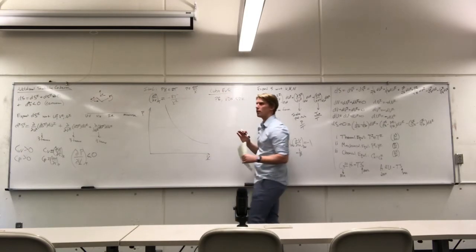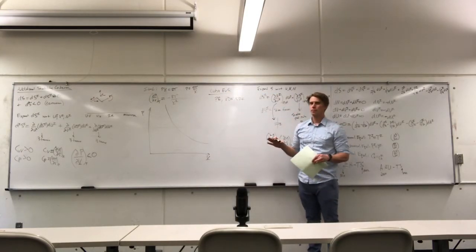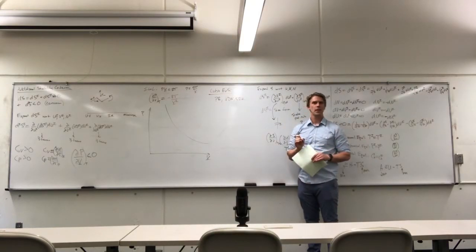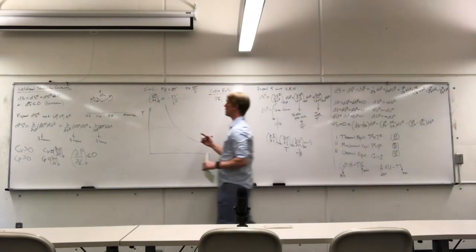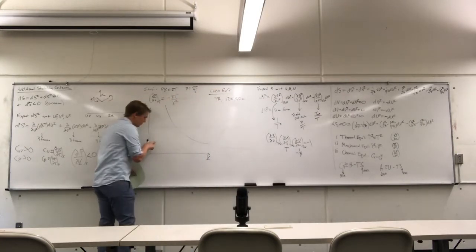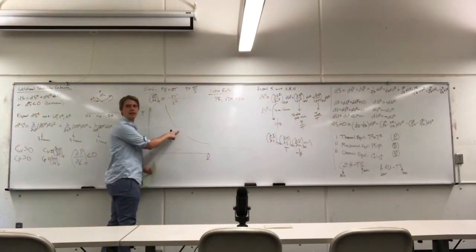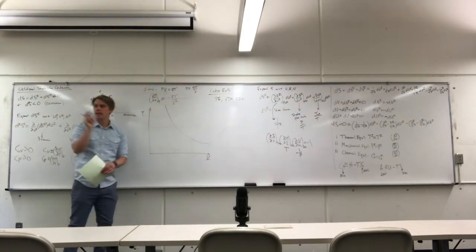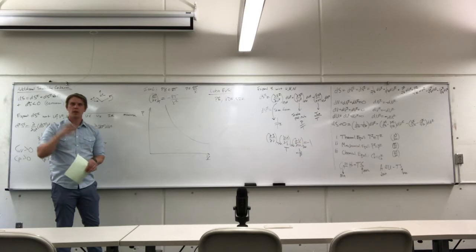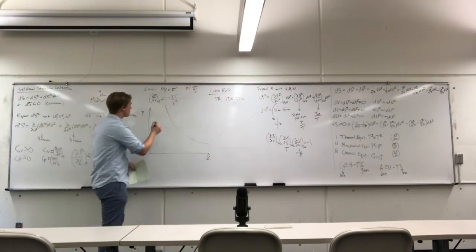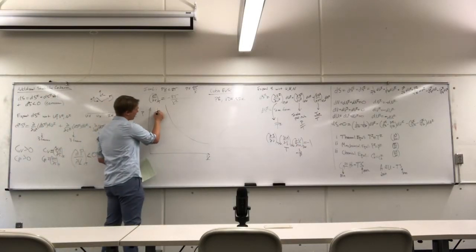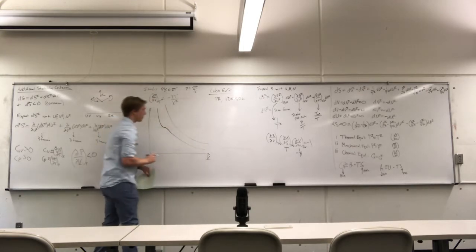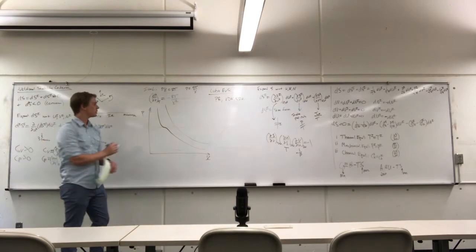Cubic equations of state are completely made up. But they are made up in a very, very convenient way. We call them cubic equations of state because at very low pressure or very high temperature conditions, they look like an ideal gas law. But they've got some extra unique features. As you cool the system down or you pressurize it, a cubic equation of state will start to have some cubic function looking characteristics.